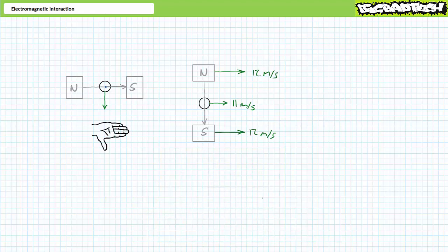For the first scenario, the magnetic field is oriented north to south, left to right, and the conductor is being pushed downwards through it. Orient the outstretched fingers of the right hand so that the fingers point north to south. Orient the thumb such that it points downwards in the direction of movement. Unless you got a weird-shaped right hand, your right palm should be facing you. This implies that voltage will be induced such that conventional current will flow out of the screen.